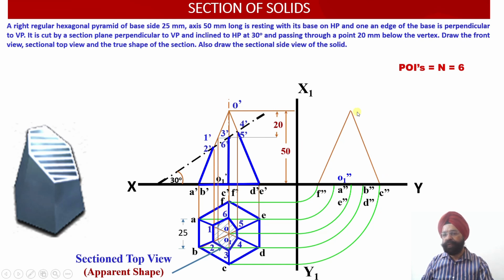Now we transfer the axis, and now we can join the slant edges over there. So this is my axis point, and then you see another thing. These are my slant generators over there. Right now I need to find the cut section. So 2 methods to do it. One way is, you have 6 points over here, transfer these 6 points in the same fashion over here, or else you have 3 pairs of points of intersection, that is 6 POIs are there.